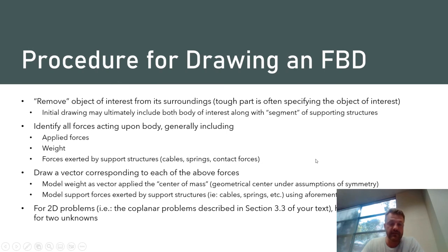And that's how we're going to close this initial lecture of the week, giving you some practice in my lab, actually doing it using the software. But you want to take the body of interest and remove it from its surroundings. The hard part is actually determining what the body of interest is. When you do the first couple problems, the book actually tells you, hey, draw a free body diagram at this point. But in general, you choose the point such that your free body diagram has an unknown quantity that you want to solve for.